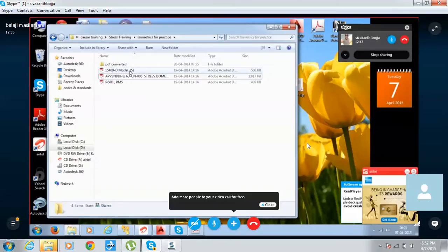If you want to insert anything, then the 20 series will be more comfortable. Equipment always starts from a higher node, about 10,000. If your system is very big, then finally we have to decide. If the system is very big we can start a 10 series or 5 series, because up to 32,000 nodes only we will be able to enter.